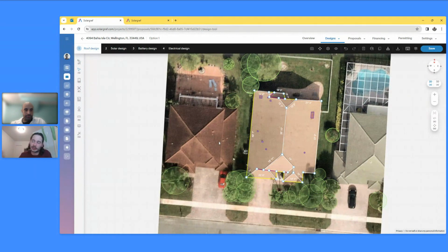When we look later in the design at solar design and production, these things are extremely accurate, because all we really need to know is the pitch of the roof, the azimuth, the height relative to the ground, trees, and obstructions. However you arrive at that model, once you have it and we have the local weather file and we're using NREL's System Advisor Model for production estimations, generally we find those to be within 3 to 5% of actuals versus Enlighten data.